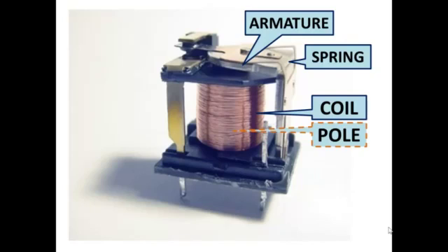Ferromagnetic material is. Another thing to remember is that the magnetic field is always trying to shorten itself. So when it sees that armature, that piece of ferromagnetic material, in the magnetic field, and since the field is trying to reduce its size, it pulls that ferromagnetic material hard against the end of that pole piece on that coil.